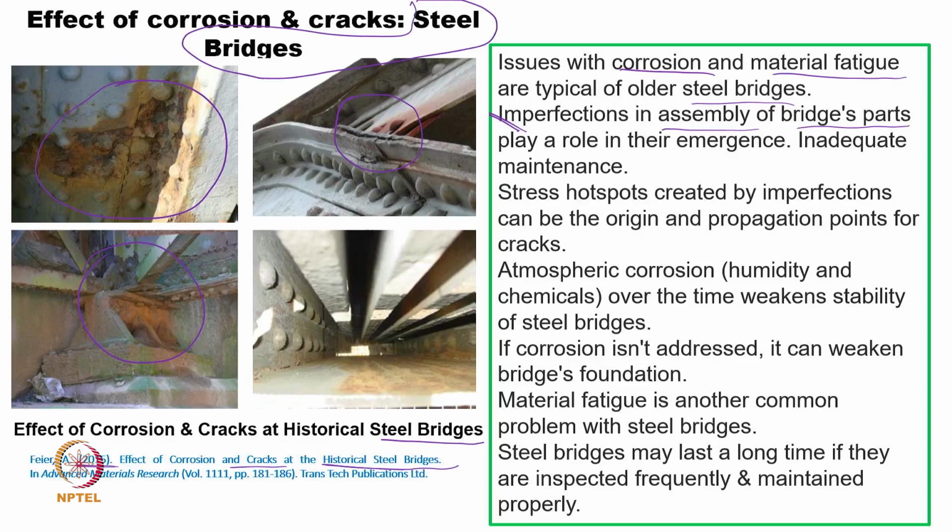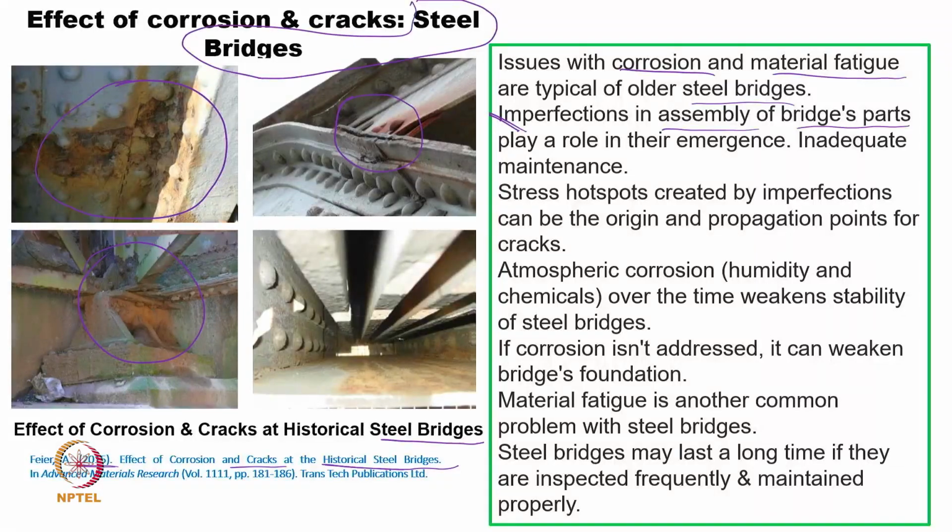Today the factor of safety is 2.5, maybe after 5 years the factor of safety will turn out to be like 1.2, maybe after 10 years maybe 1, and after that failure will occur. So, this is a dynamic process. Whatever we have done initially, that is a static design, but dynamic, every time the situation will change, and that is why we say many times we need to look at real-time maintenance.